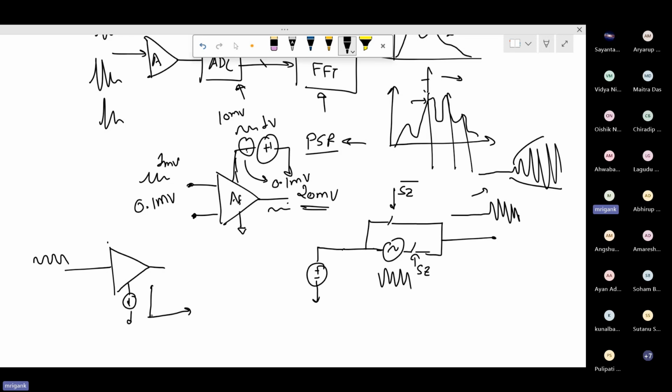Can anybody check if a ramping signal is available in LTSpice? I think we can generate a PWL file that can ramp. I used the ramping of voltage using PWL in the comparator resolution setting. There I used ramping using PWL. So then somehow you have the PWL file, that option is available. Loading the PWL file as a source, that is available.